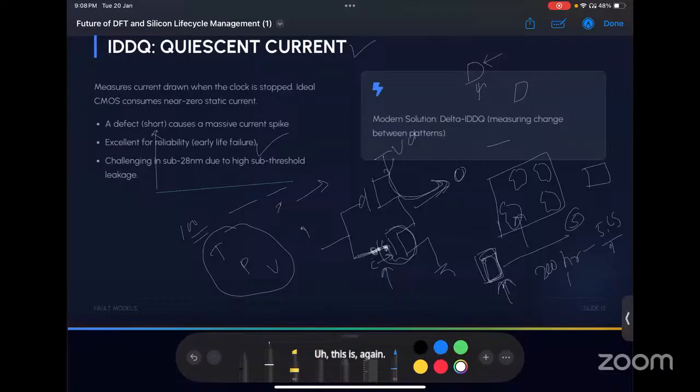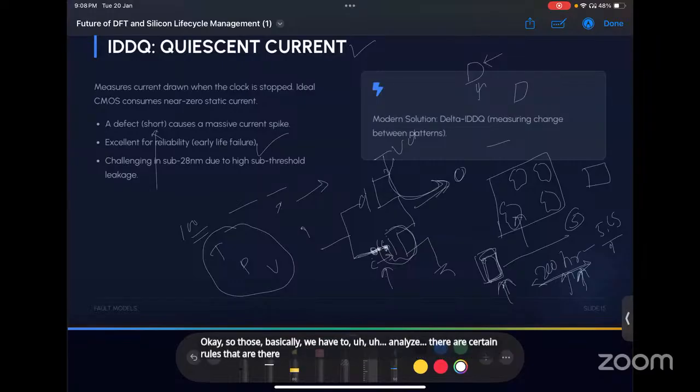This is again different. I just gave an example here. Let's say if you run 200 hours, it is considered to be around 5 to 6 years of usage. It depends on the application of the chip: automobile, or, let's say, in space, the chips used in satellites and all. Each will have different criteria and a different kind of hourly or aging-related basis. We call it aging simulations. There are certain rules with respect to which we analyze that hour-to-years ratio.